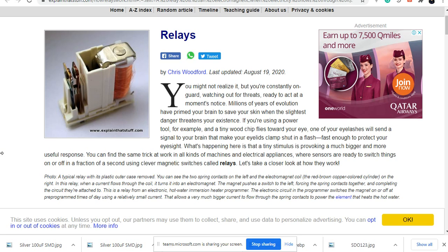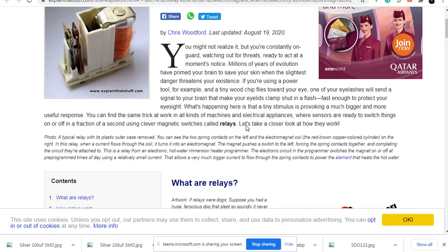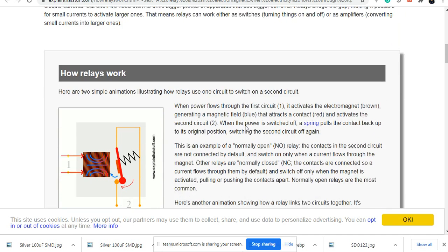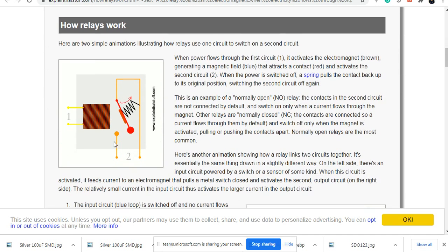A relay is actually an electromagnet. So you all know what an electromagnet is. A simple material, an iron core or maybe some ferrite material, and on that ferrite core you have some winding done on it, this one. You can see in the small animation what is happening. This is a relay coil, this one where my mouse is hovering. As soon as I give a DC current to this one, this fulcrum, the red color fulcrum, gets attracted. Why? Because you all know whenever there is a solenoid or an electromagnet, it is going to have some force of attraction.